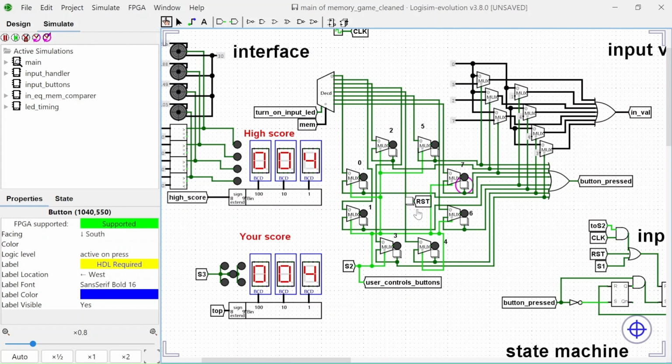If you haven't realized already, the last press of a sequence doesn't show up. It can probably be fixed by using the falling edge detector. This is because it will keep the LED on while holding a button down, instead of detecting it as a press immediately, which will switch out of state 2 and stop the LED. However, this doesn't work here due to other components interfering in my design, and I would probably need to add a flip-flop somewhere to make it work.